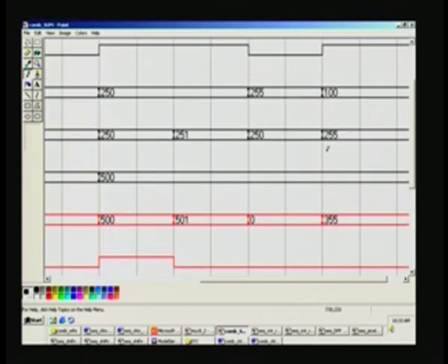And once again, before that one, I deliberately made enable sum low once again, just to show that it is still working. At any point of time you can make this. So when it is made low, once again it ignores. You see there is no sum here, and preset value is an input condition, so it continues wherever it was left. So here it is 505, that's absent here. That is the reason, enable sum is inactive here, and once again it is made active here, and all this, mind you, are stimulus applied through the test bench.